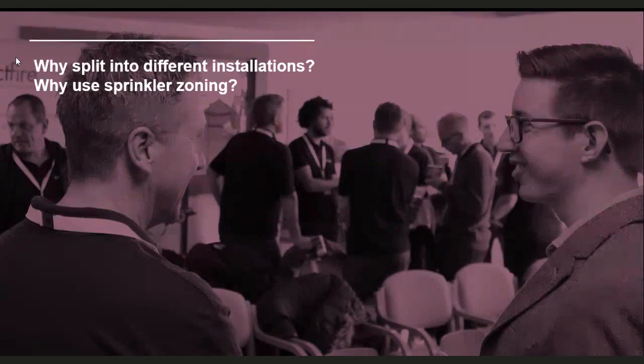So splitting it into different installations, I've kind of already covered really. It may well be due to convenience. So you've got, say, different buildings. You'd have a different installation for each building, which keeps everything nice and separate, so you know what is protecting what.